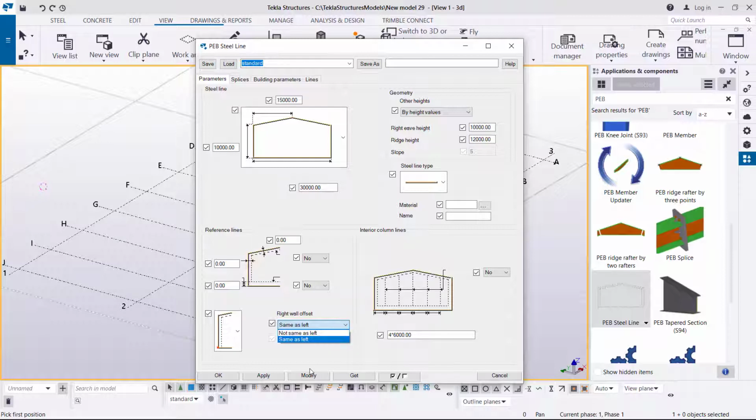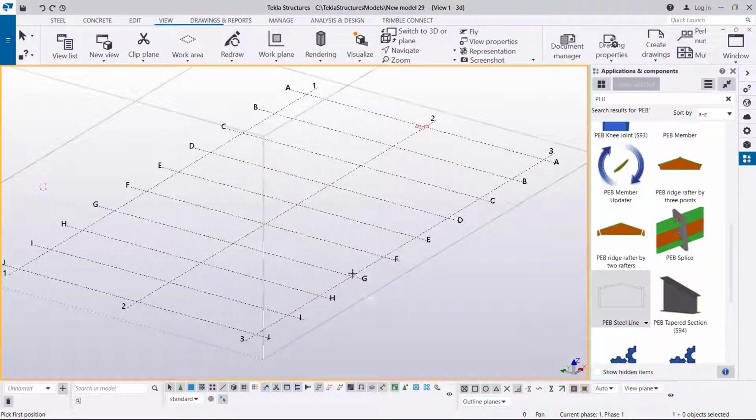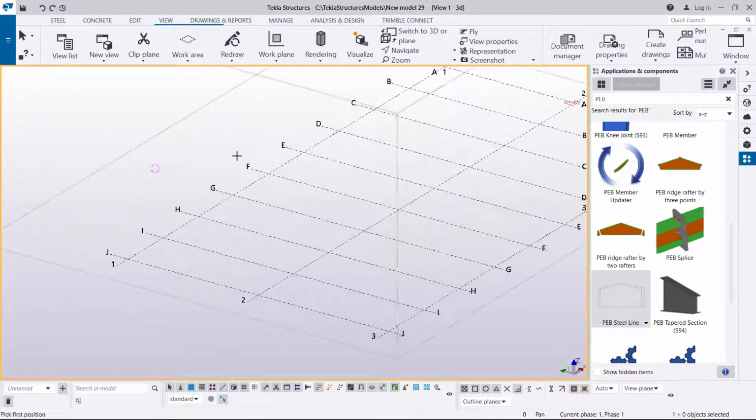So let me first assume the settings I have are correct, and I'll go ahead and click apply. If I click apply, you'll see my cursor is active and carrying some instructions to be applied in a particular position. Also at the bottom here, Tekla Structures requests that you pick a position so that we place the instructions there. If we pick that particular spot, we get the second instruction to identify the second position. So we'll identify this position here as our second position.